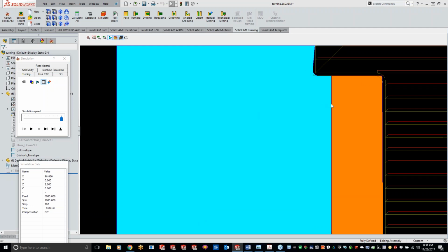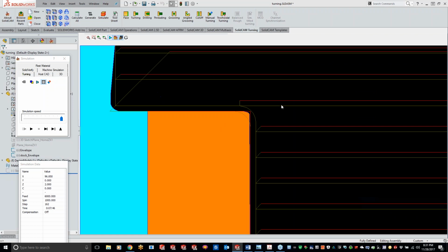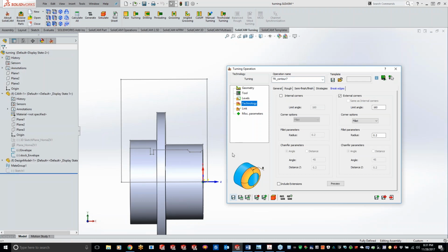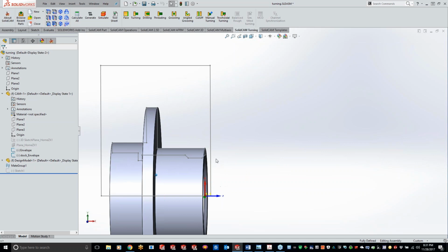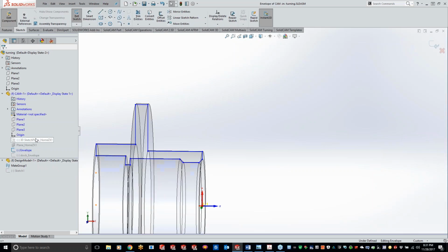And you can see, we can zoom in here. We have our small fillet in there for you guys. So you can add that in there. Now, there's a lot of guys that want it manually added in there, which is 100%, that's fine. So all you have to do to change that is come in here and just go back to your SolidWorks portion of it, and you'll highlight the envelope, and you can see as I have my cursor over it turns orange here, and we can just do edit sketch.